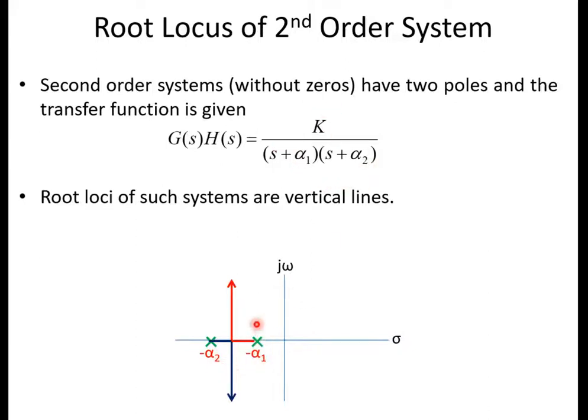So that is why, if alpha 1 is, say for example, 1, then it is minus 1, and this is 2, minus 2. So in between there is a breaking that happens, and because you know that the root locus branch will start like this. Okay, like this is the arrow. If you want, you can put even the arrow also.